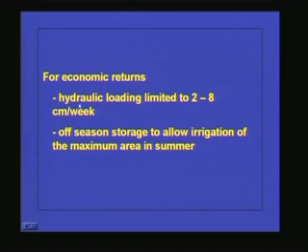And for economic returns, a hydraulic loading of 2 to 8 centimeters per week is recommended, and off-season storage to allow irrigation of the maximum area in summer is essential, because in the winter the water consumption will be less. So we may have to store the effluent for irrigation purposes in summer.